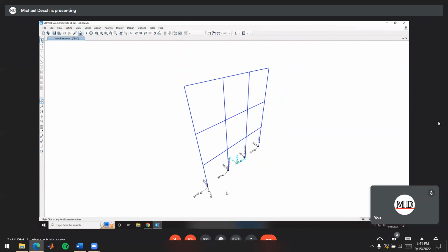That's because the moment is shown with this double-headed arrow here. The way they draw that is it's drawn about the axis it rotates about. And we use the positive curling right-hand rule here to show the positive direction of that one. And that will show you those. So in the 2D frame there, the moment's about the y-axis, so it plots the arrow along the y-axis there.